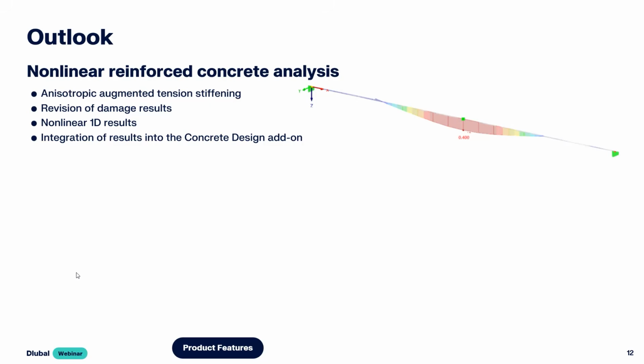Therefore, we have a calculation between the angle of the reinforcement to the angle of the stresses. Furthermore, there's also a calculation of the distance between an integration point on the surfaces to the reinforcement point over the thickness.